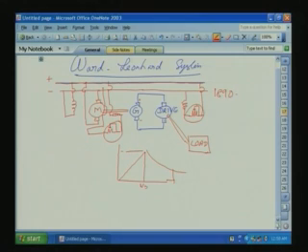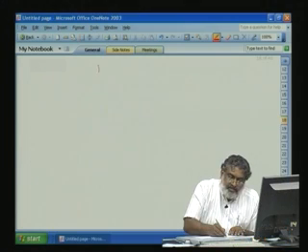But what we want for high dynamic performance applications, we want to control through phase control converters or variable voltage control using PWM converter, so that fast control is possible, and we are not going to introduce any resistance. So, dissipation should be less, so efficiency should be maximum. That means fast dynamics and maximum efficiency. How can it be done? See, let us again go back to the torque speed characteristics. How is it done with the voltage control using controlled converters? But let us take the torque speed characteristics.